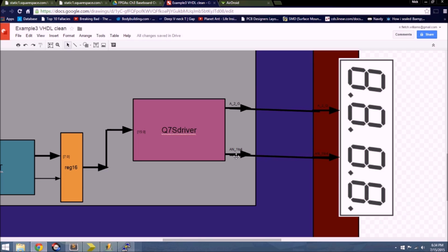So what you're supposed to do is use this enable line, which is active low, so you can independently turn off any of these. You turn on this one for a short amount of time, use this to display what value you want there really quickly, then quickly mux to the next one, display whatever digit's supposed to be there, then here, then here. So you alternate: you display this digit, turn off the rest of them, display this digit, turn off the rest of them, and so on. And you do it so fast that the human eye can't notice the blinking that's actually going on in reality.